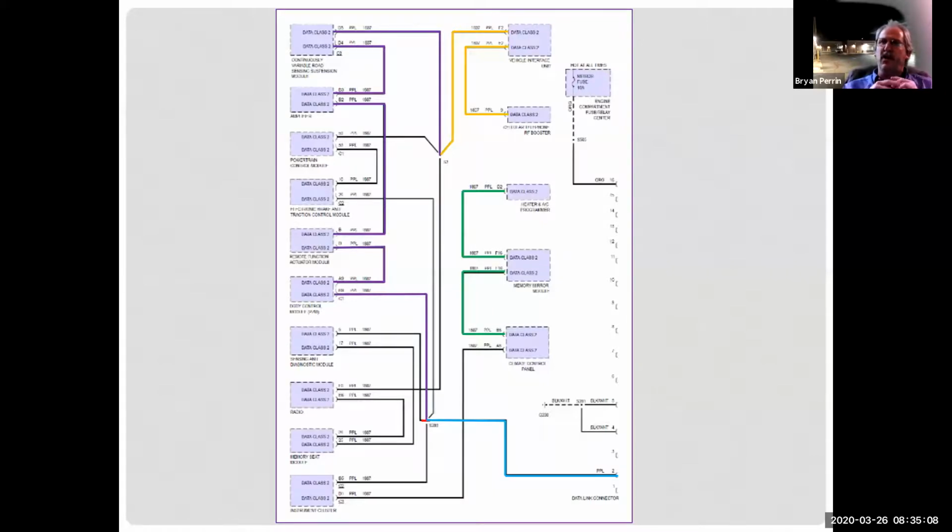So when I get into OBD2 a little bit, we're going to break down what OBD1 is, what OBD2 is, and what is not OBD but still has a 16-pin connector. We're going to break down what actually makes OBD2, because it's very specific. It comes down to when I have to set a code, how I have to react, what monitors I have to have, and how I have to monitor the vehicle. So Yaman, you have a question.